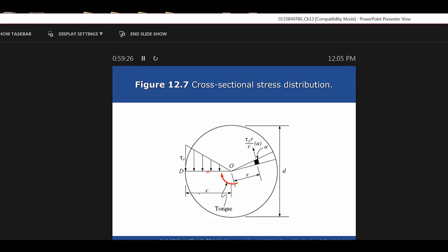Or you could have your machinist turn it down to 2.48. Really, do you want to do that work? Because then you're probably going to have to order a special pulley to put on it, because the pulleys tend to match the shafts. So not exactly. Actually, the pulley diameter might be 2.48, and then you have to press it on. It wouldn't be quite that big or that small, but you can press those on. Okay.